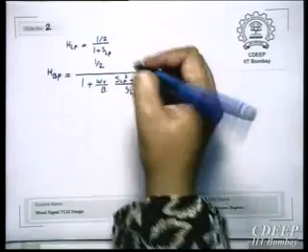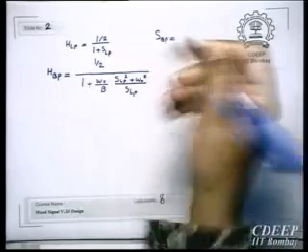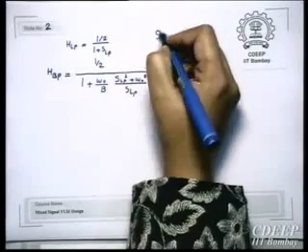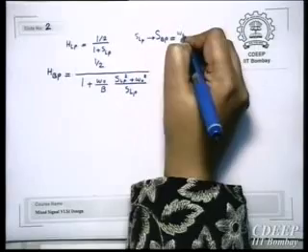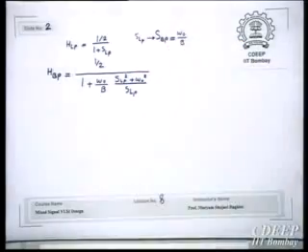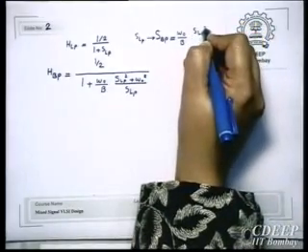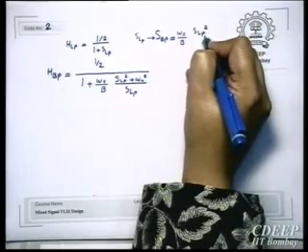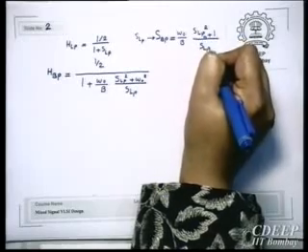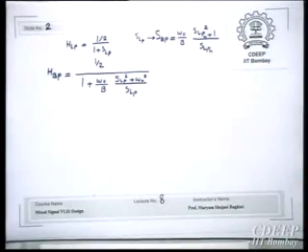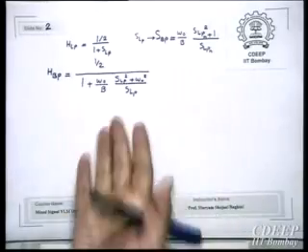In band pass, what we do is replace S_LP with S band pass, which is equal to omega 0 upon B times S_LP normalized plus 1 upon S_LP normalized. This was the relation, right? Then S_LP normalized is S_LP upon omega 0.